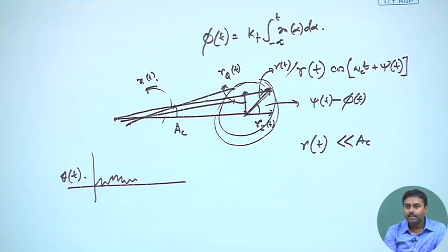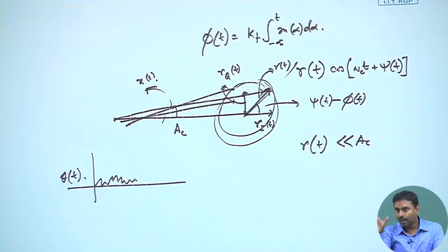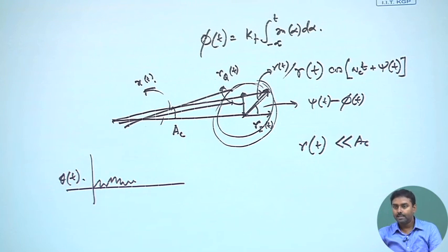That might create a huge effect in the phase variation, and the phase variation is the theta t which you are trying to track, where the FM is modulated. Differentiation of that is the demodulated signal. So, if this varies a lot, some impulses will be generated. These impulse noises are termed as click noise, and we will see that.